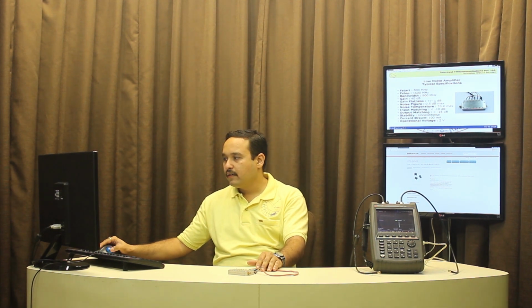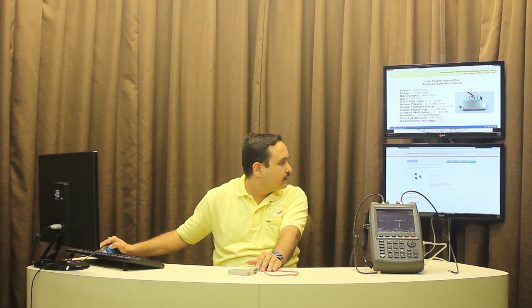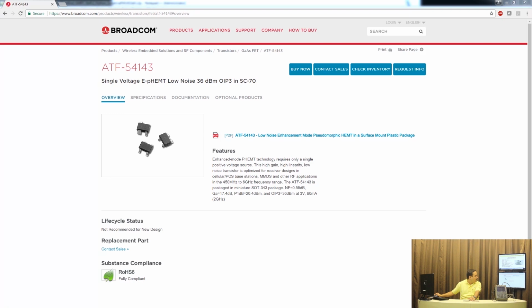So for that, have a look at the screen. I am choosing one particular transistor, which is a HEMT transistor from Broadcom with the number ATF54143. This is also a very common transistor for low noise amplifier designs around L-band or mobile bands, for example.